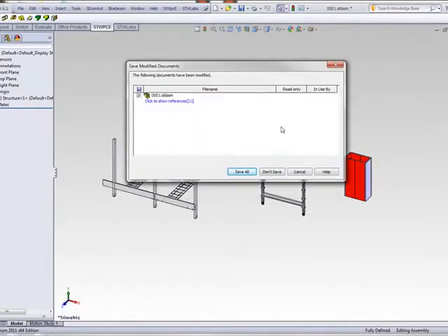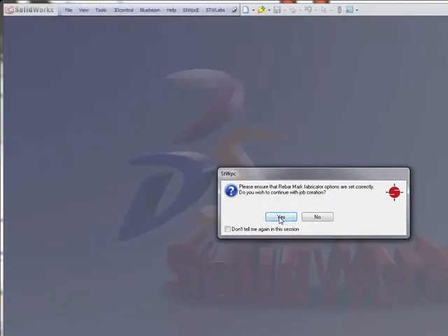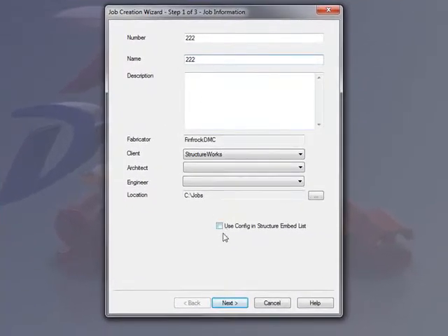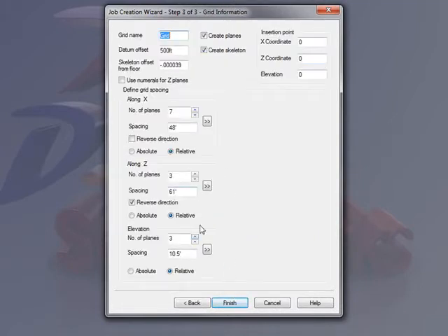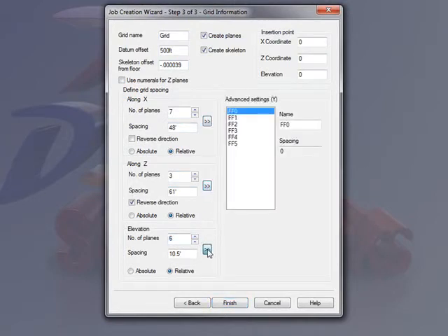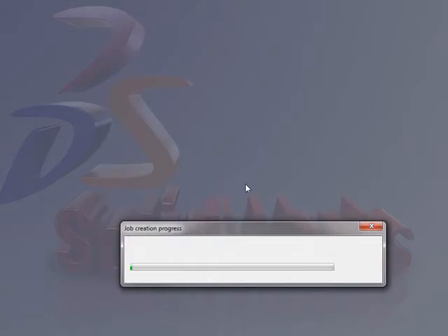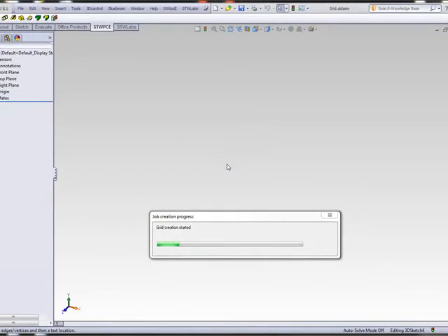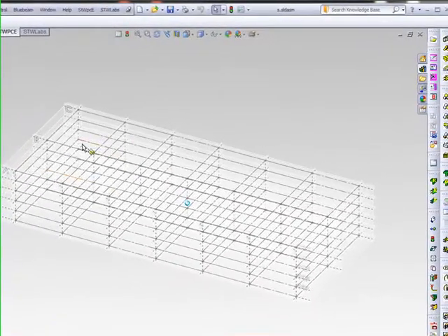And what I can do is, when I create a new project, I'm just going to create a new project and leave all this, and we'll give it 6 floors. Okay. Once this new project is created, we can go ahead and copy the production assemblies into this project prior to inserting any products.